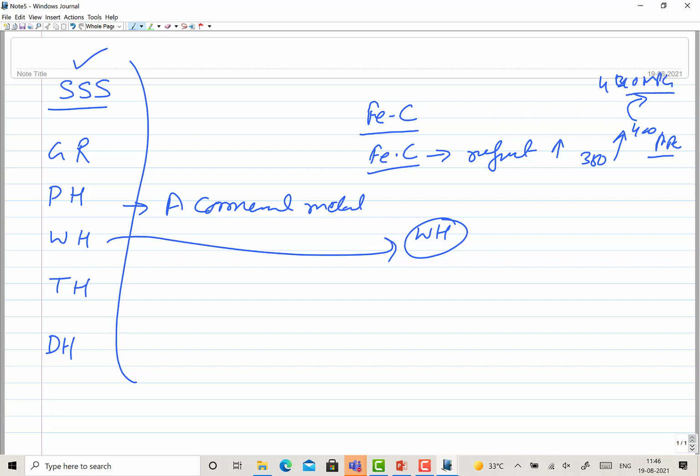Okay, so the main strength it was gaining from the solid solution strengthening, then marginal increase took place from the grain refinement, then further minor increase took place from the work hardening. So there is a possibility that most of the strength, say 70% is coming from one mechanism, and say the second mechanism is contributing 10%, and third mechanism is contributing 20%, right?